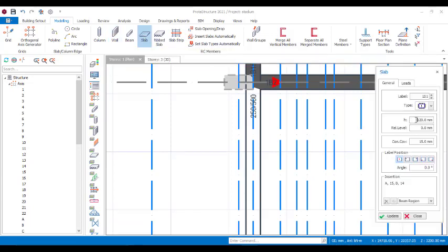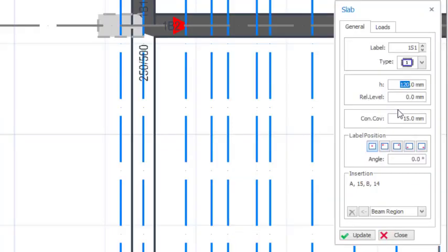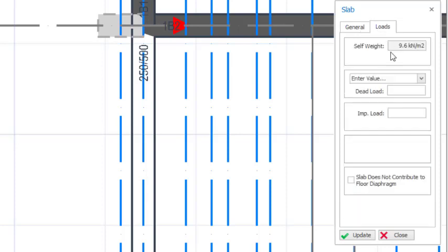So the thickness of the slab, just as we said right now, should be 400 mm. And then the cover, I'll change the cover to 30 mm. If the thickness is 400 mm, that's the last thickness, so the cover of 30 is good enough. That's a stadium, so that is why I'm having that kind of load.